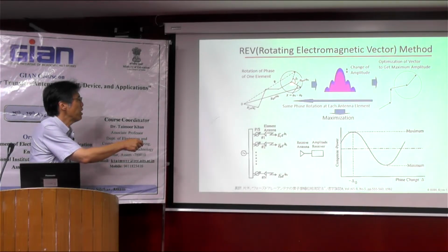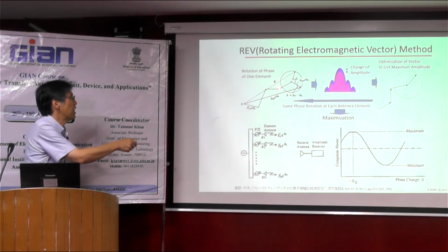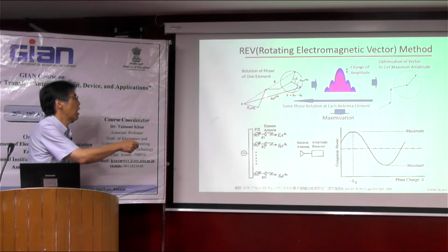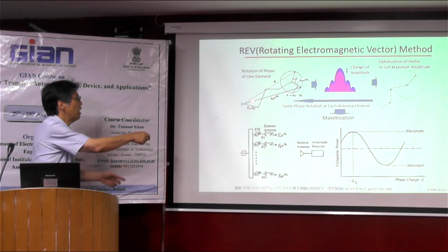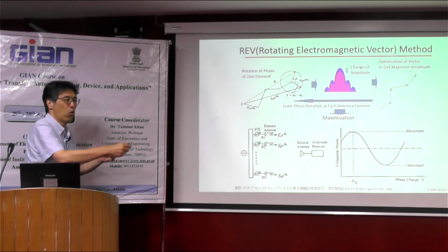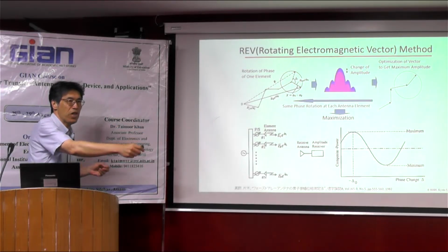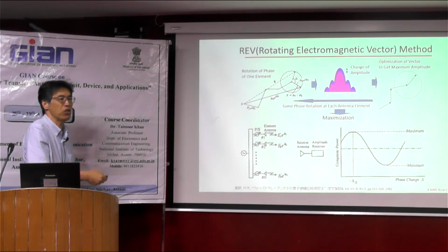And when we find the peak power with the best phase, we change the other antenna and rotate the phase again, and again and again. In total, this phase creates only one line vector, so the received power will be maximum.